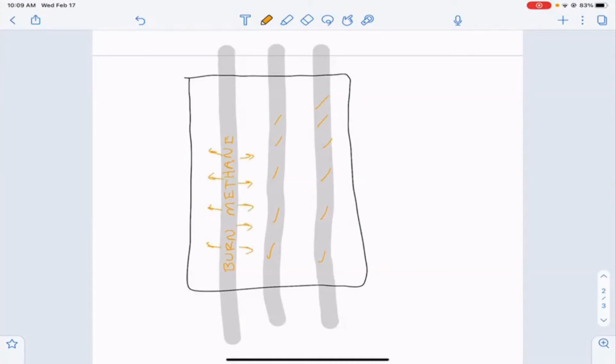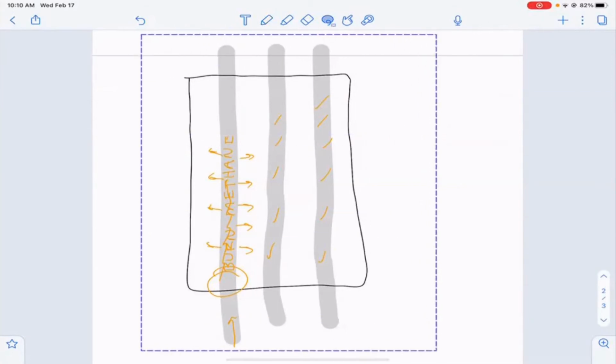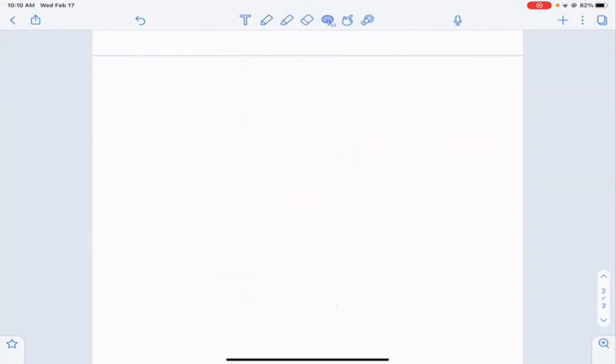And sometimes, at the bottom, there's literally fire in the column, right? You'll flow oxygen and methane. It hits this really hot reactor and it'll ignite. And then you have a flame that goes some way up the tube, and the rest of it is just hot gas. It'll be CO2, water, and whatever excess nitrogen and oxygen from air is hanging around. Okay. So, just FYI, when I say an internal firebox, that's the thing that I'm talking about.